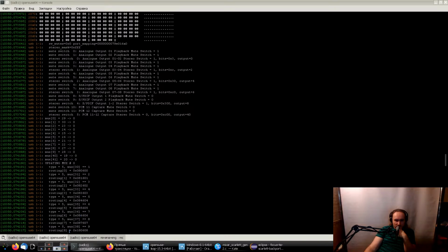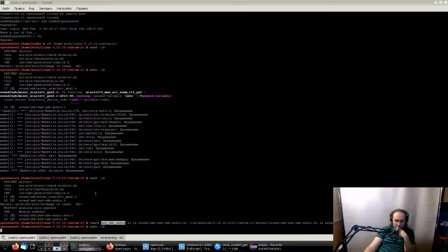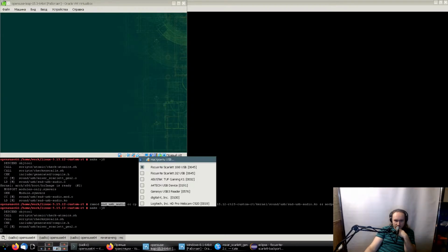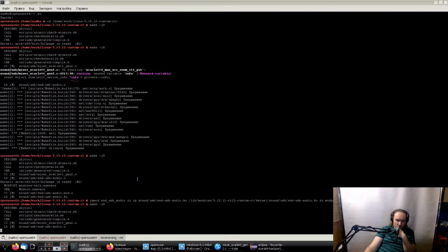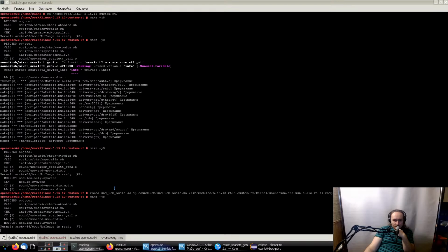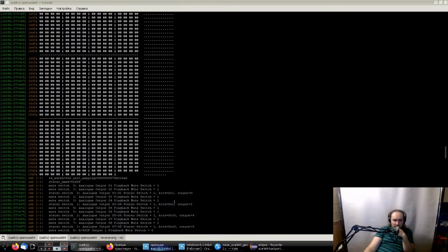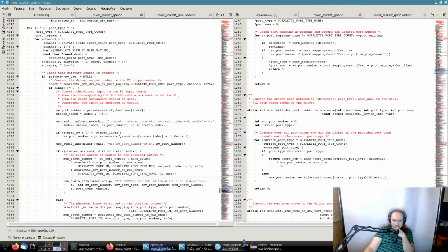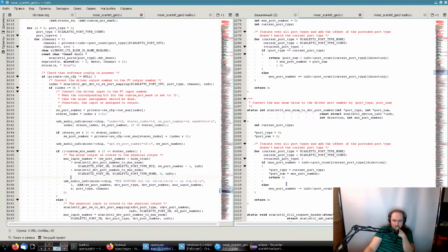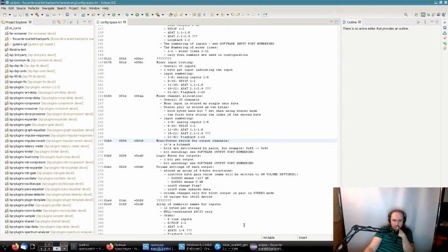Let's look again at what's happening. Then we need to just recompile the kernel driver, disconnect the device, and relaunch all the stuff. Probably we will have missed something, and we will check at this moment what's happening. We'll find out. I also can check the mask stored there at this moment. I just need to recall the offset.